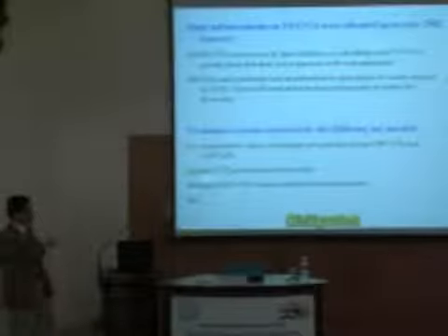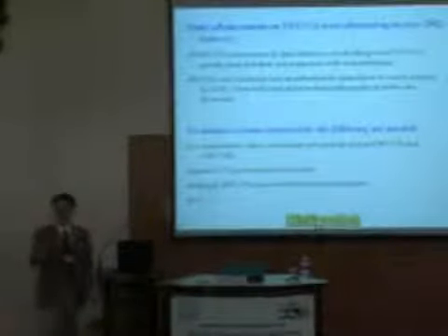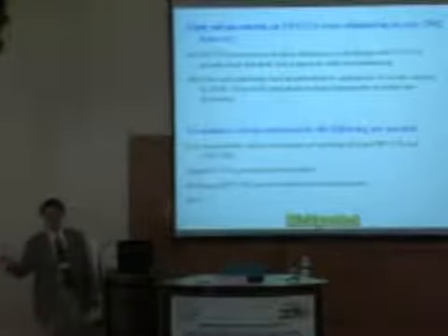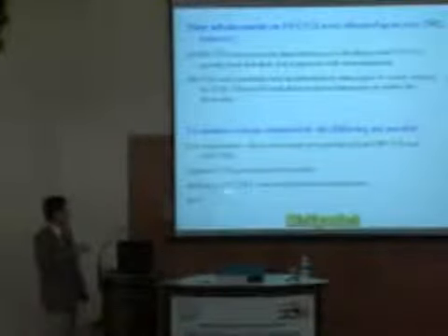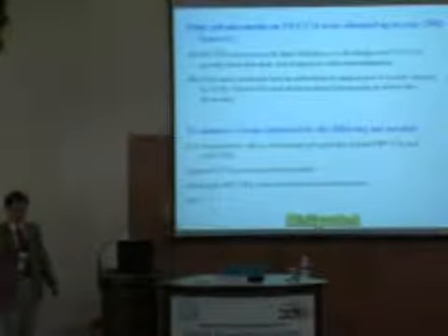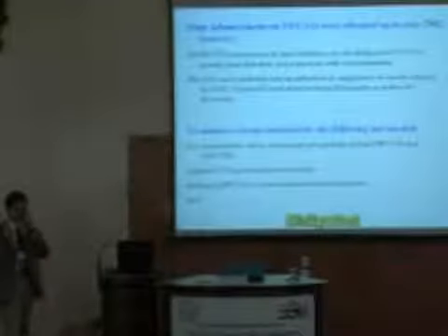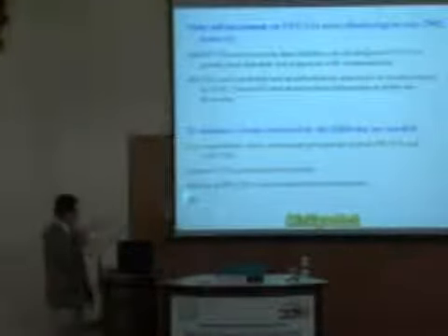And you will need to be able to deposit carbon nanotubes across a pair of desired electrodes. For instance, within the chips, you might have 1 million pieces of the electrode. You want each pair of the electrodes to have only 1 nanotube aligned across them. And also, you have to be able to sort single wall carbon nanotubes into semiconducting tubes or metallic tubes, so that you can choose only the semiconducting tubes for your applications. And etc. The list will be very long.